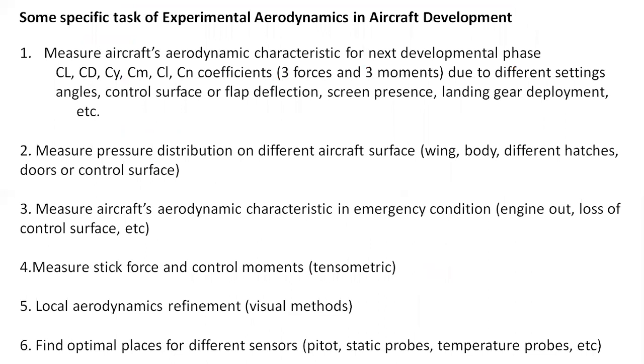Next slide. Our specific tasks of experimental aerodynamics in aircraft development. First and main task, this is measuring aerodynamic characteristics for the next development phase. This is CL, lift coefficient, CD, drag coefficient, CY, side force coefficient, and CM, CL, CN, these are moment coefficients: pitch moment, roll moment, and yaw moment.